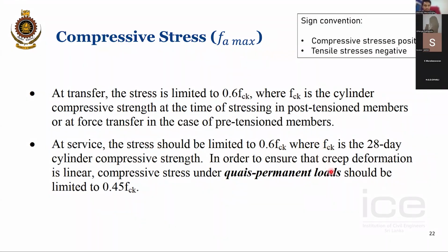And there's a case called the quasi-permanent case. Quasi, QUASI, the spelling is again different. Quasi-permanent means the loads are permanent, just like when you place a beam, apply the finishing screed, and before you apply the full load. In that case, if you are considering the stress conditions, you can use a maximum compressive strength of 45% of the characteristic strength, a little bit less than this one.